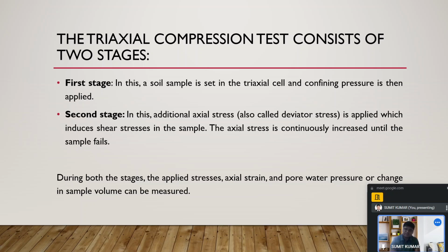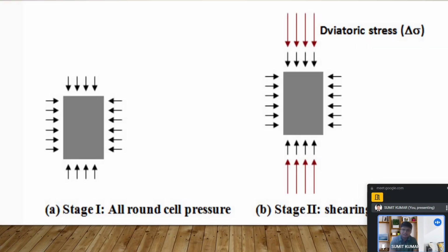In a similar way, if we know the values of sigma 1 and sigma 3, and if we know the soil type is cohesive soil, we can consider the value of phi as 0, so we could get the shear strength parameters like C and phi, and the converse is also applicable for cohesionless soil. So that point will be very clear, I think.